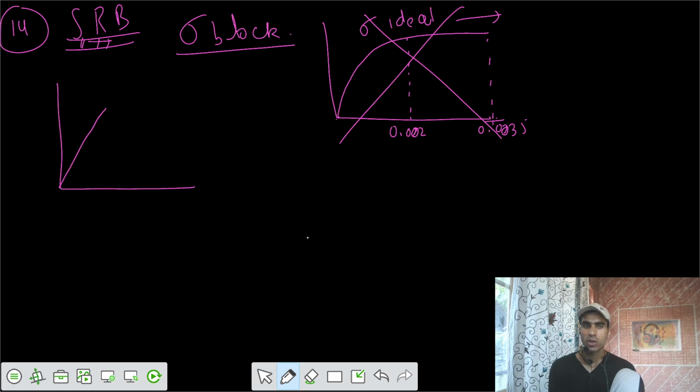As per assumption 3, we can take a triangular, trapezoidal, or rectangular stress block, but the results out of that should be in perfect agreement with the test results of the actual one.